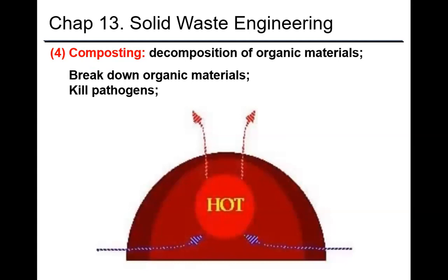So for the waste that is putrescible, right, you can degrade it. People can use composting facilities to extract the energy out of the organics. Basically, you can break down these organics and also kill the pathogens. What happens is that you can introduce air, right, oxygen plus nitrogen. The bacteria can utilize this air, propagate, and degrade these organics to reduce the BOD that's coming out of it.